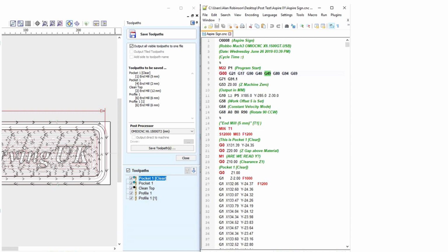currently in the spindle. It is okay for the H number to be 0, an offset value of 0 will be used. Omitting H has the same effect as a 0 value. G44 is provided for compatibility and is used if entries in the table give negative offsets. It is an error if the H number is not an integer, is negative, or is larger than the number of carousel slots. To use no tool length offset, program G49.